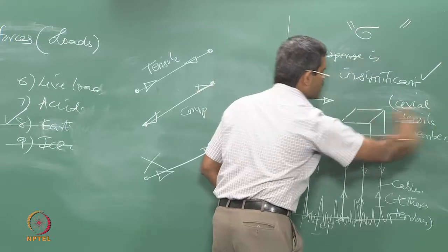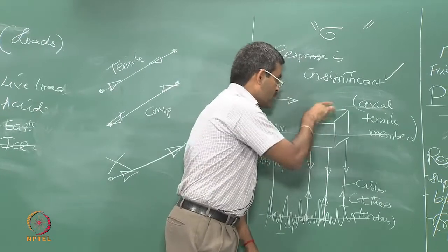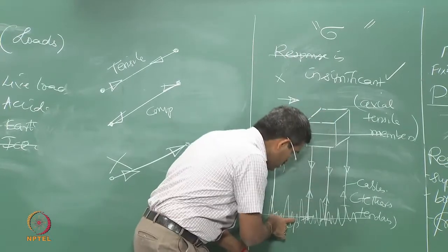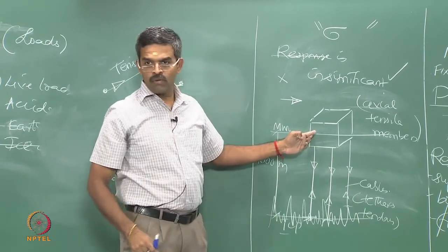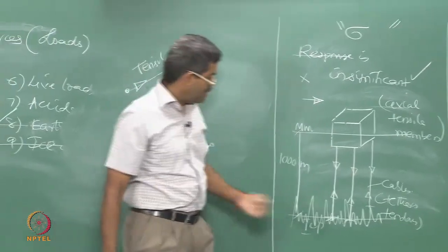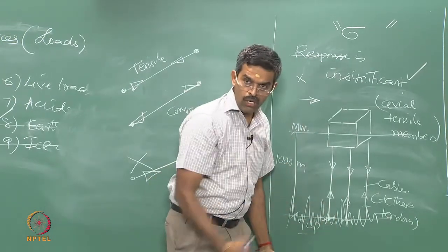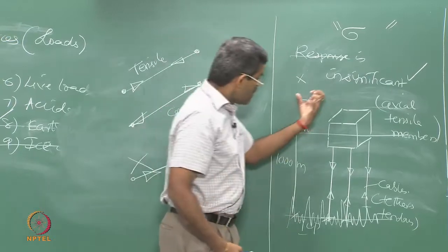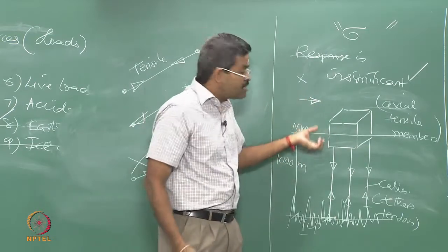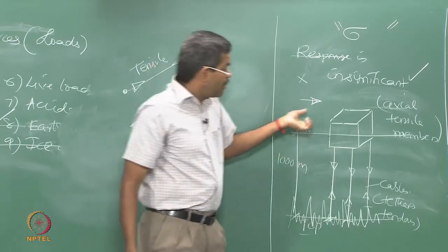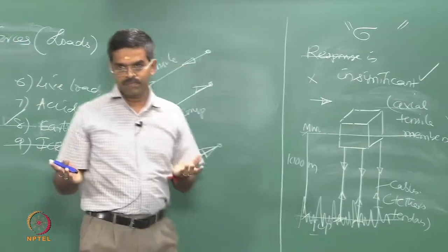So, there is a lot of freedom given to the structure in terms of displacement, but what happens to the structural displacement when such forces do apply at the bottom, which is a kilometer down from the water level? Interestingly, when the seabed moves up and down, the cables are either pulled or slacked. When the cables are pulled or slacked, the stiffness of the system changes, because there is a change in buoyancy of the system. When the buoyancy is changed, the response of the system is significantly altered.